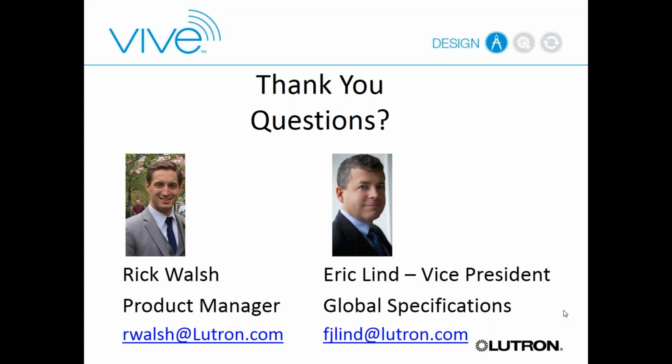A lot of questions coming in. Talking about the Clear Connect, our 434 frequency band, how does that work in construction equipment? The way we rate our range is actually we've got a number that says that we can meet it through construction materials. So unless you're building a solid metal wall, we actually get some benefits from that 434 megahertz band, in that we can propagate through construction materials better than a higher frequency like 2.4 gigahertz. So again, that builds into that reliability story that we've talked about before.